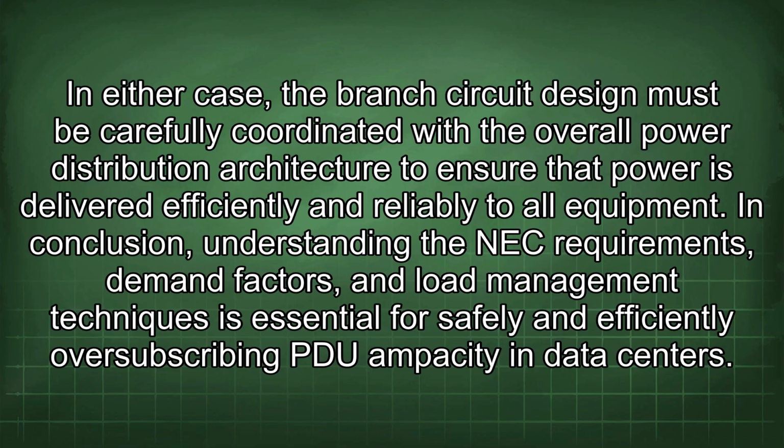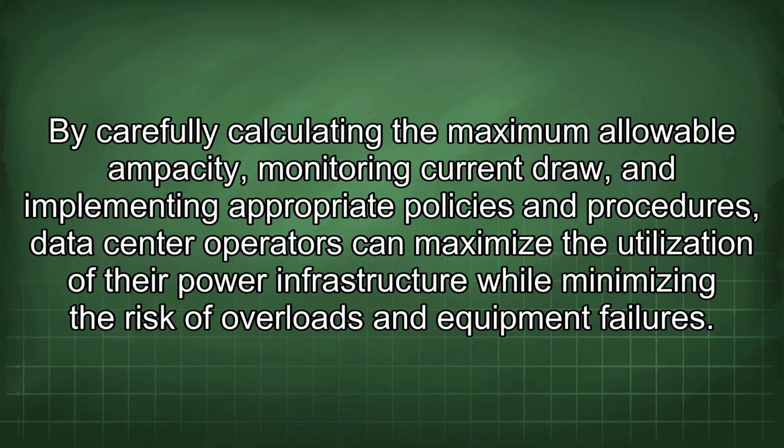In conclusion, understanding the NEC requirements, demand factors, and load management techniques is essential for safely and efficiently oversubscribing PDU ampacity in data centers. By carefully calculating the maximum allowable ampacity, monitoring current draw, and implementing appropriate policies and procedures, data center operators can maximize the utilization of their power infrastructure while minimizing the risk of overloads and equipment failures.